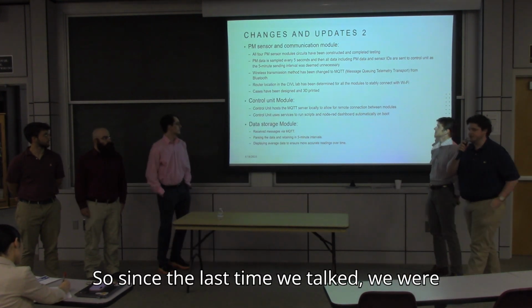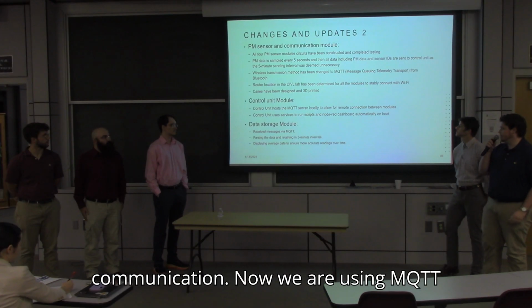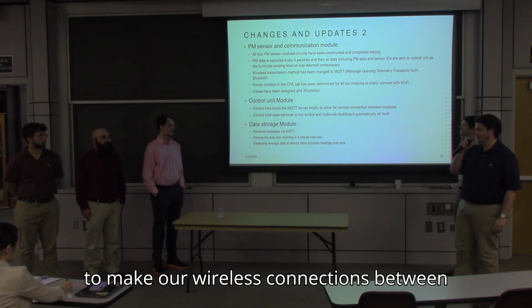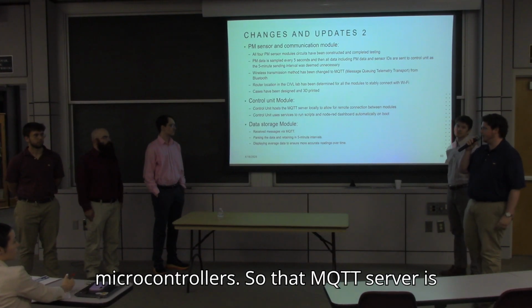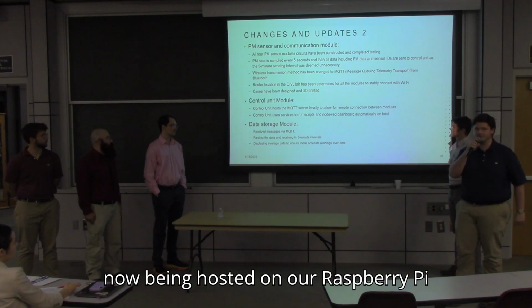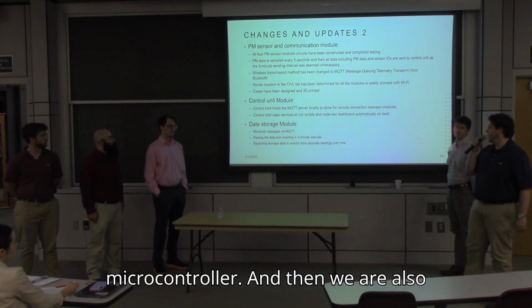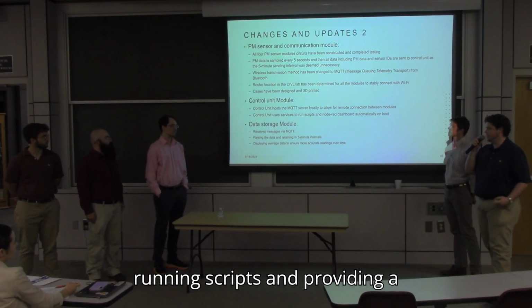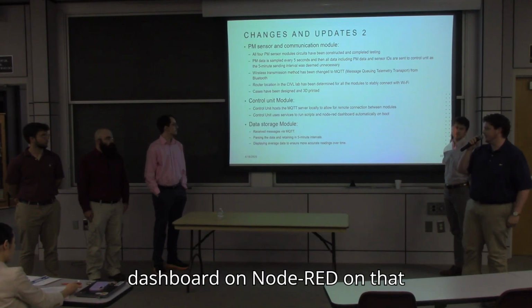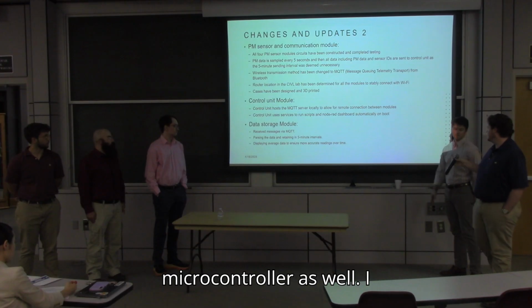So since the last time we talked, we were planning on using Bluetooth communication. Now we are using MQTT to make our wireless connections between microcontrollers. So that MQTT server is now being hosted on our Raspberry Pi microcontroller. And then we are also running scripts and providing a dashboard on Node-RED on that microcontroller as well.